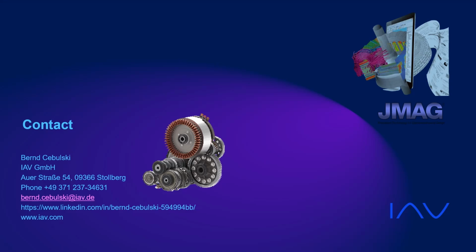This is the easiest way, but there's also something like a BH view right now. If you make a point view in JMAG, you can not only look at the magnetic induction, but you can also do a BH view, magnetization against magnetic field strength, which also shows you by the curve whether there is demagnetization or not. But to convince our system engineers and my managers, because they are not so much into this electromagnetic stuff, you look at the open circuit voltage because everybody understands that.